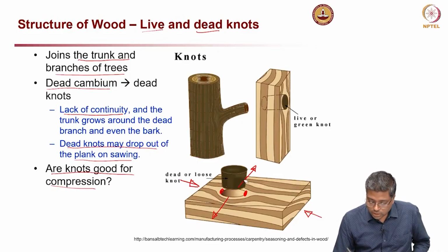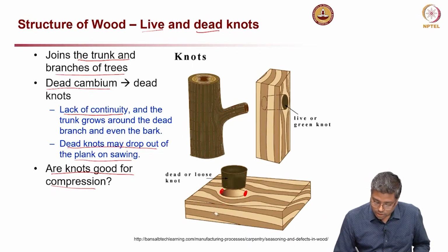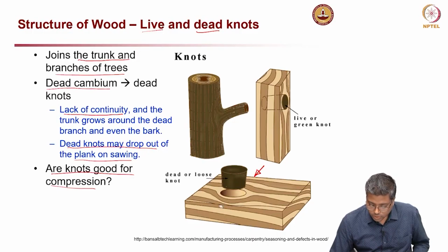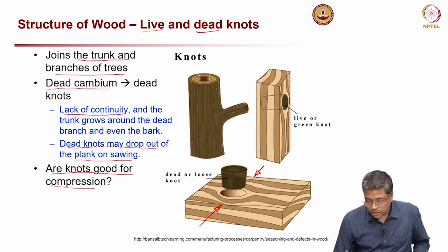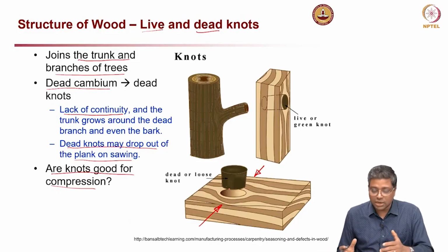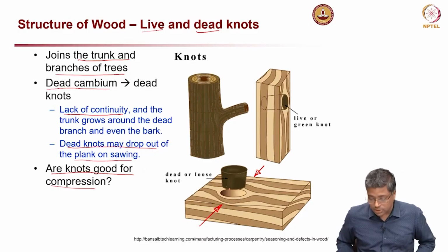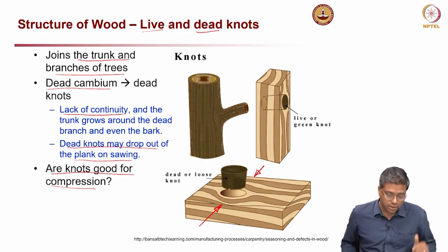That is one thing. Now, if I apply a load in the other direction, let us say I am applying the load in this direction, then also there is a compression and it might push the knot out, and again you might experience a stress concentration. But depending on the direction it might not affect much in this direction, while in the other direction which I showed you earlier, it will definitely have some impact on opening up or cracking of the wood along the grains or between the grains.